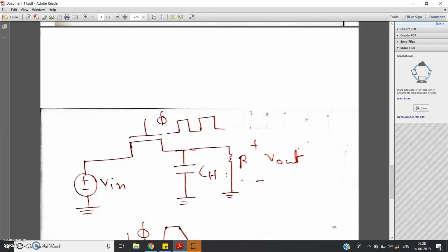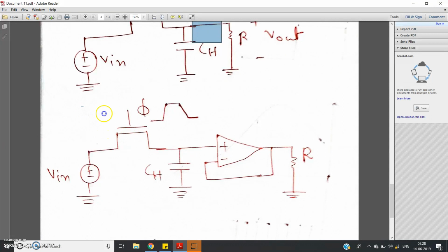So we have to give a certain circuit in between the capacitor and the resistor which has no voltage gain, that is unity gain, or which can act like a voltage follower. It will isolate between input and output, but it will pass the input voltage to the output. So what can we do? Simple, we can use that unity gain amplifier or unity gain buffer using an op-amp, which we discussed at the initial part of this video. So we can implement this circuit.